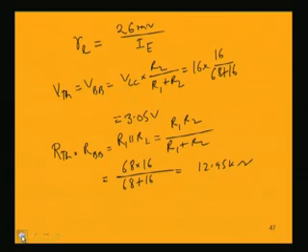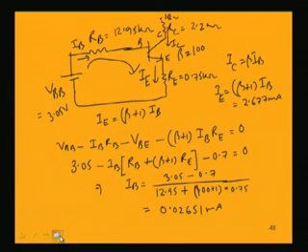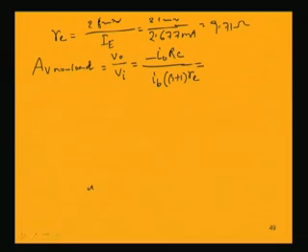Because if we look into the circuit, the Vi is equal to IB into this resistance beta plus 1 RE, and the current which is flowing through RC is the same current beta IB, which is nothing but I naught, because I naught will be now same as IC without load. So, multiply it by RC, that gives the output voltage, and I naught is nothing but beta times of IB. So, minus beta times of IB into RC by IB beta plus 1 RE.